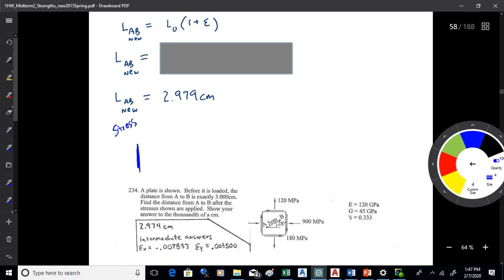Let's say we're going to go 28 degrees from this plane. We will get to this plane right here, but the stress acts normal to the plane. So that's sigma x1 for 28 degrees. You all with me there? Because the stress, by definition, is normal stress, it's normal to the plane.